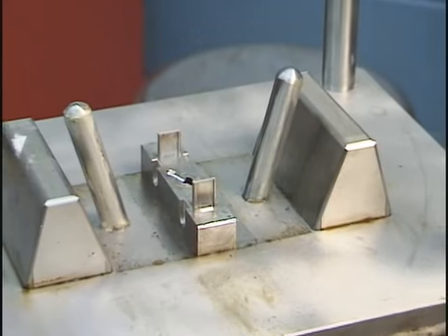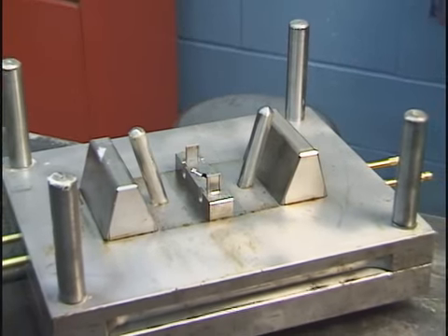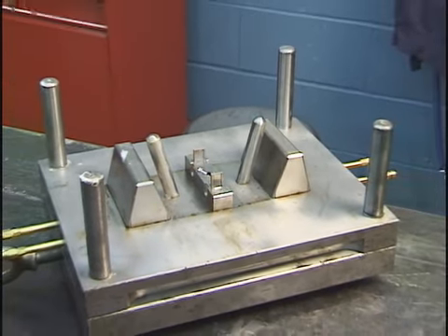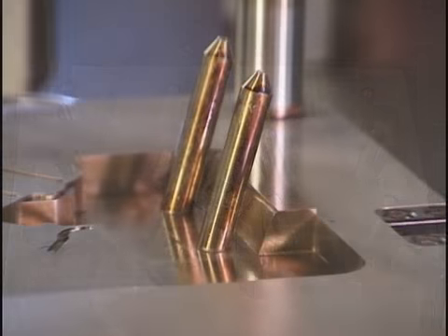Increasing the angle of the actuator pin increases the length of travel, yet more wear is induced on slide components. With this in mind, high production molds typically use actuator pin angles of 10 degrees or less.